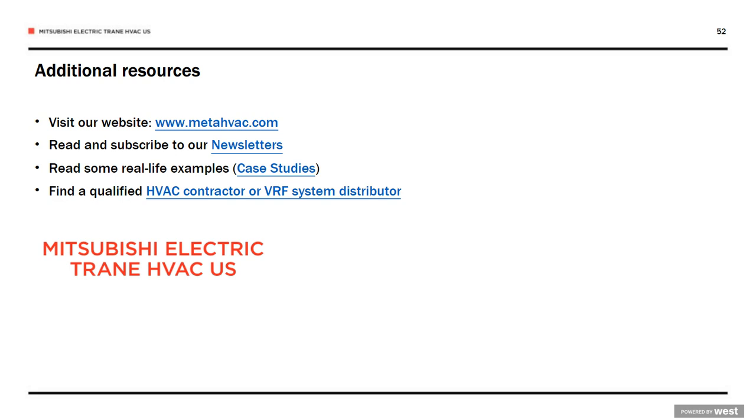And on the maximum side, there's flexible ways to design a system, especially with water source VRF, that can enable you to install VRF in 40, 50, 60-story buildings. The second one, call it restriction, if you will, is rooms or applications that require a lot of air changes. So think operating rooms, clean rooms. Those are probably not the best application for a VRF indoor unit, just due to the fact that you can't get enough CFM through it on a regular basis.